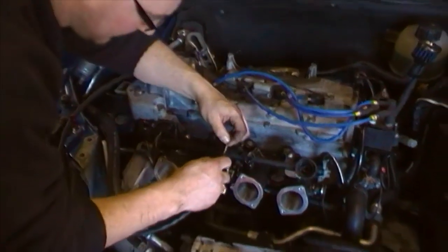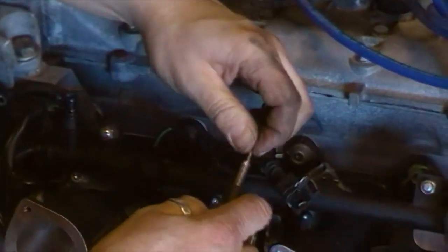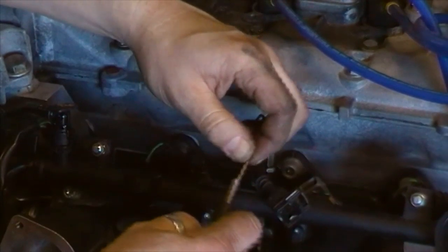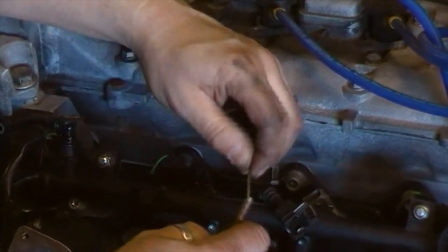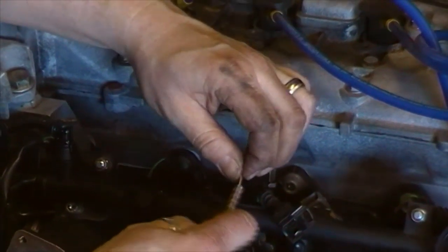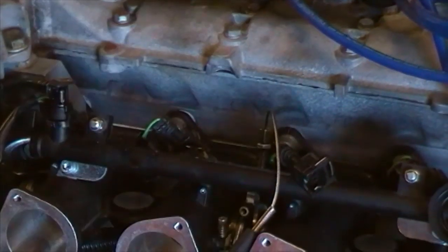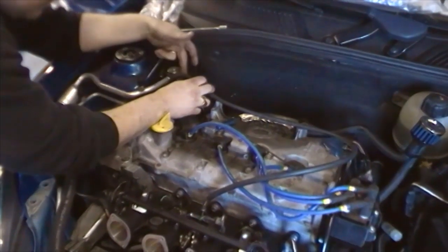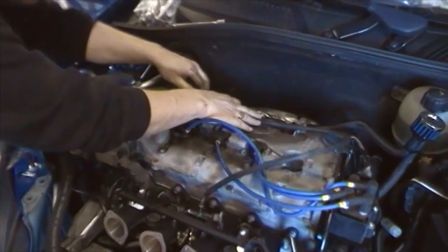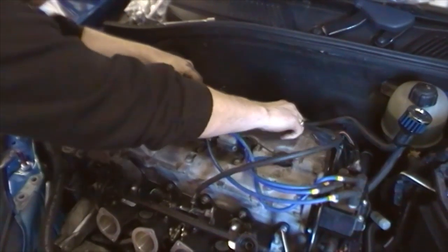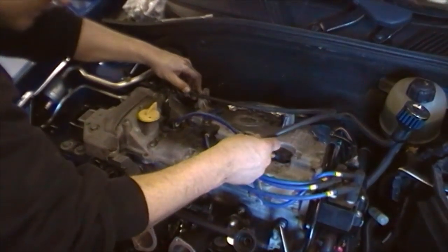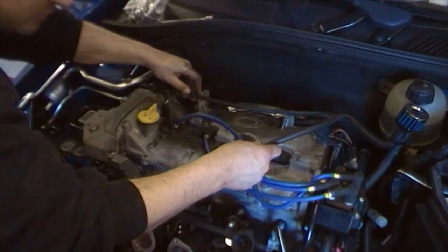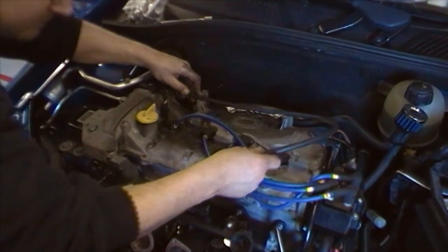You'll feel it get a little bit stuck as it goes through the bulkhead, but very carefully work that around and it will go through. Having got the inner cable through, we now put a cable tie around here onto the engine hoist and install the two P-clips on here and here, securing the cable, leaving a little bit of free play here should you need to reroute in any direction.